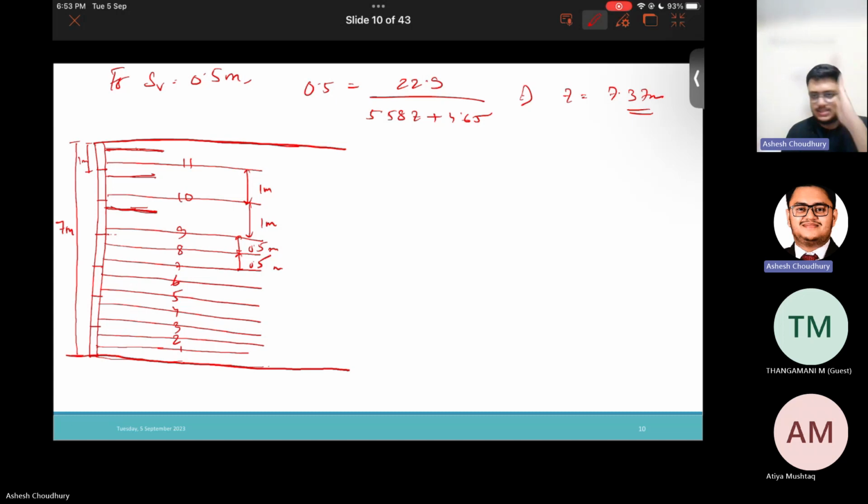Else what will happen? See, this is the facing block. We are putting the reinforcement here, right? So there might be some tension eccentricity. Due to this pulling, this facing block can get displaced. Just to prevent that condition, we provide some small reinforcements here also, to prevent eccentric loading on the facing block.